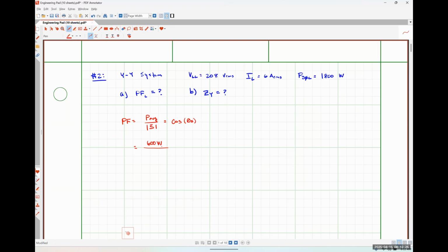Okay. Well, let me actually, I'm gonna change this slightly. So I put the 600 there because I was looking at it on a single phase basis. My problem with line voltage and line current is that if I want my total complex power, that's going to be multiplied by √3, and so it's not going to be an easy thing to divide by 3.